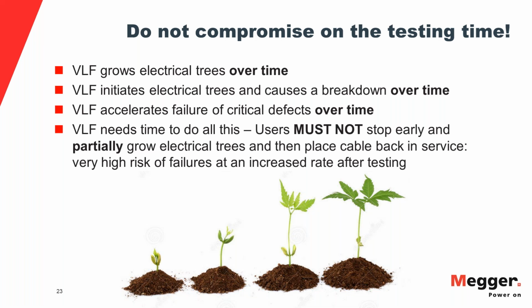impacting your cable very negatively, because then you energize again, you started the acceleration process, and you stop before you actually could give the test enough time to really say, okay, yeah, this electrical tree would have failed within 60 minutes, and this is how you missed it, and then you re-energize, and a few weeks or months later, you got an in-service failure. So you need to do the test for the proper testing time. Never cut short on the testing time. That's one of the biggest mistakes you can make.